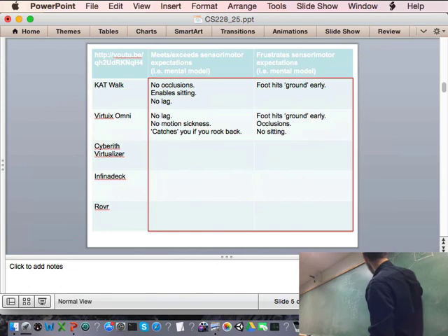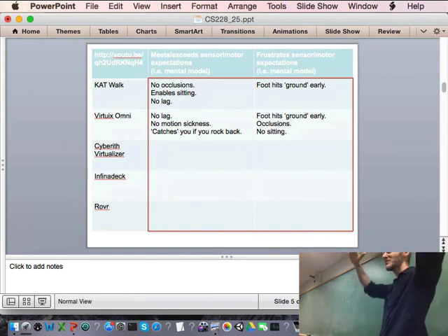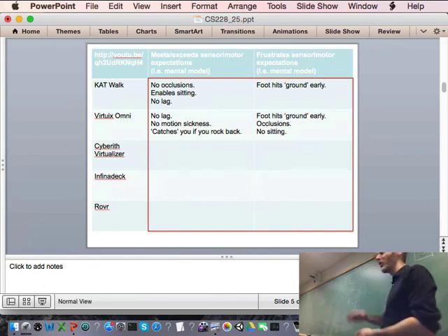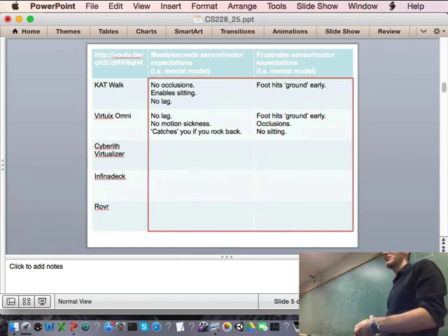So the robot senses the fact that the user is in the process of jumping and acts to compensate the weight, right? So those three pillars actually move the three arms up and try and follow at exactly the right velocity profile what the user is doing. And that velocity profile that the robot is moving at is meant to try and produce a particular sensation in terms of the ring while the person is jumping.